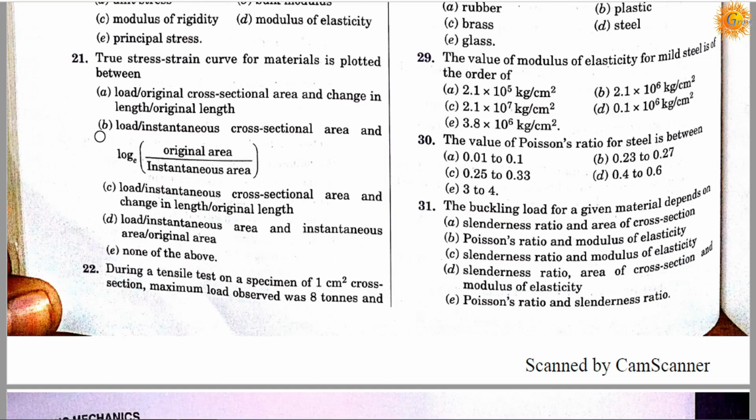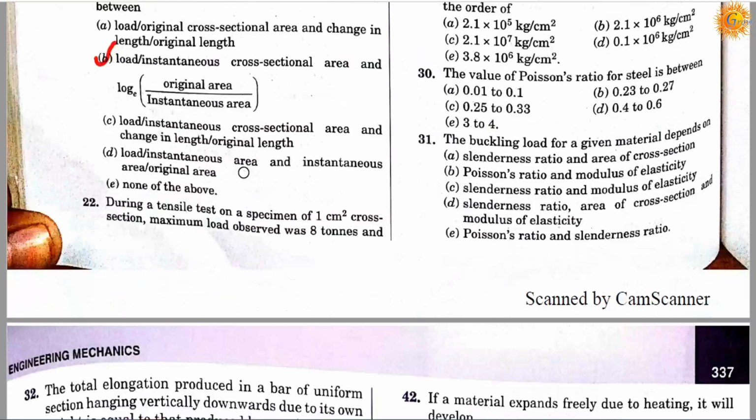Correct answer is B, it will be load over instantaneous cross sectional area and log of original area divided by instantaneous area.